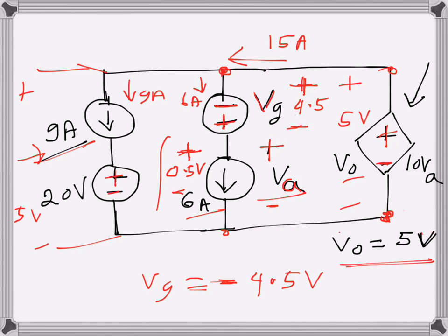So in order to counter that, I need a voltage drop of plus minus here. So I will erase that 9 ampere, which is not needed to be written there. So that's there. It will be like that, 15 volts. So that's the voltage drop across it. So 20 volt here and 15 volts here. So after the subtraction, it will be 5 volts in this direction, because 20 volt was in this direction and 15 volts was in the other direction. So subtracted, so 5 volts remain here.